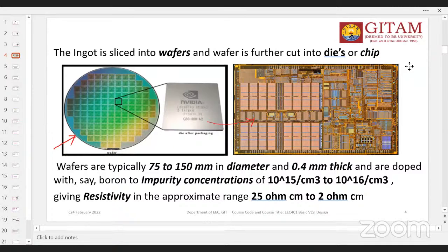Instead of source and drain, we consider it as one or two terminals, and we place on top of it some kind of diffusion material. It will act as a resistor. So the point is that transistors are modified in such a way that they act as a resistor or capacitor in addition to the transistor's operation. That's what we can say.